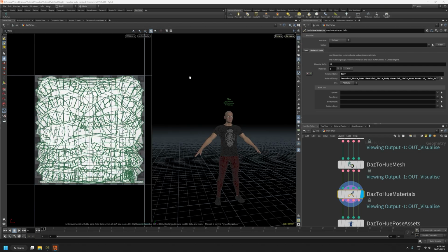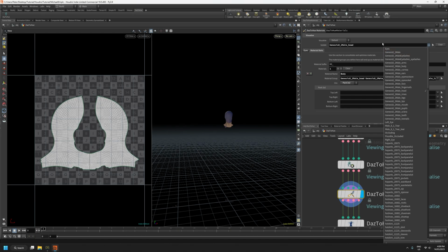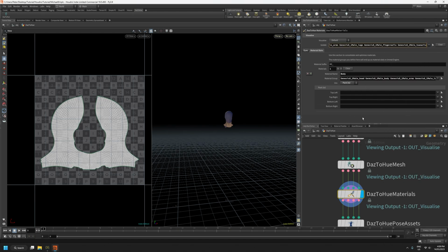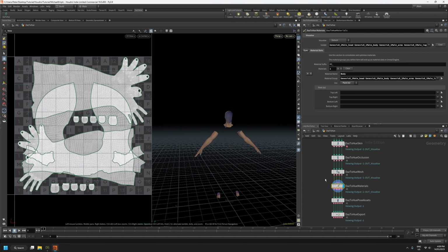What I'll do is bring back the UV layout, and just so we can really see what's going on, I will isolate the characters. Actually, as a shortcut, I can just copy that. Now, bear in mind there isn't much, in fact there isn't any of our character's body left, and there's not much of the legs left, so this isn't a great example of optimizing in this case, but I just wanted to show you the process. At some point, I am really keen to add more UV layout options and also texture baking options here in Houdini, so that we can pretty much just auto pack any part of the geometry and bake the textures across. But, that's a future plan.